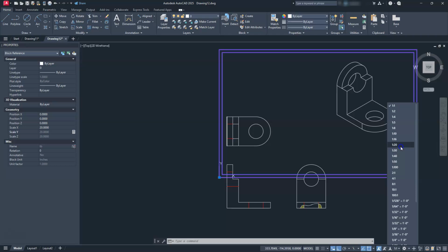If you're figuring out which method you're going to use, I use the standard method, annotation, or I like to use the paper space method, right? Try to choose between one of those. Although you can mix them, I like to keep it simple. So if I'm going to use the standard method, I use it for my whole entire drawing. Annotation scale is super simple, and paper space is super simple. But if you're going to use standard, stick with standard on everything. So in this one, I think I will go ahead and show you standard just so you don't get used to seeing the annotation scale, right?